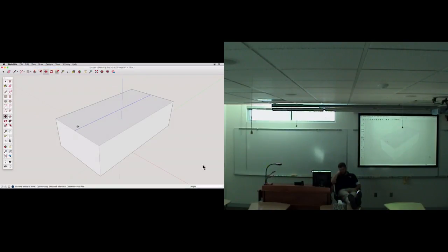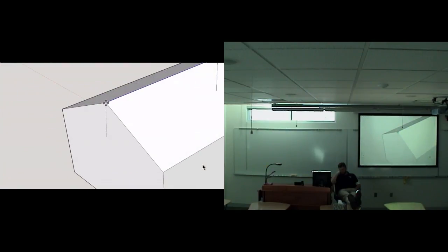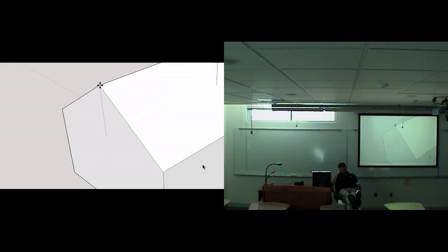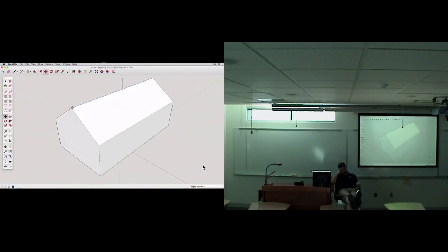Make sure the edge is selected, then, using the Move tool, click once on the edge to start moving it. While moving it around, notice that the edge snaps to a blue dotted line. This is an indication that you're moving the edge straight up, which will result in an even roof. Click to finish. In SketchUp, the red, green, and blue axes will help you to draw and move correctly in 3D space. Let's try it by creating a chimney on the roof.